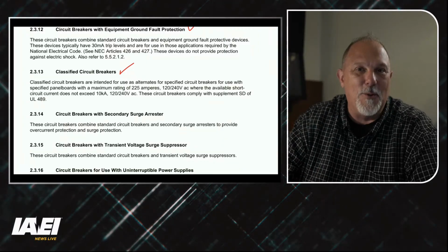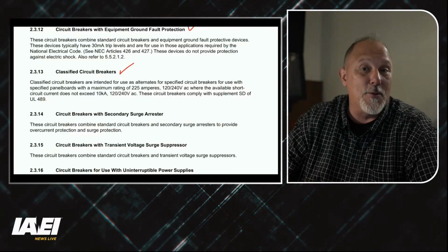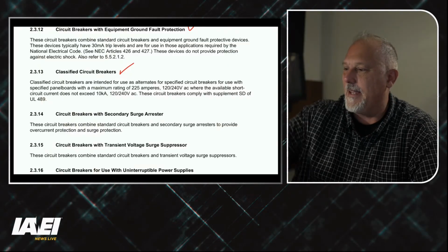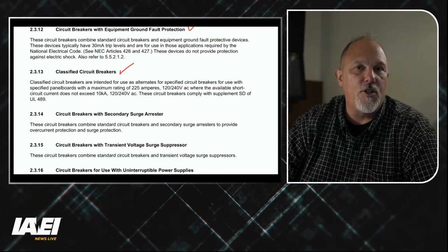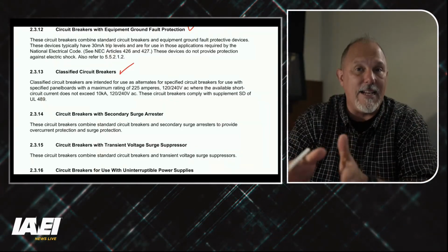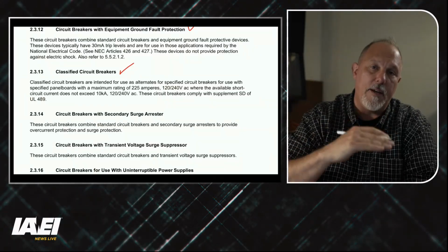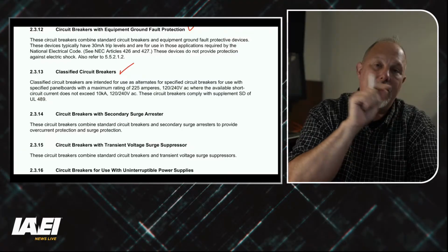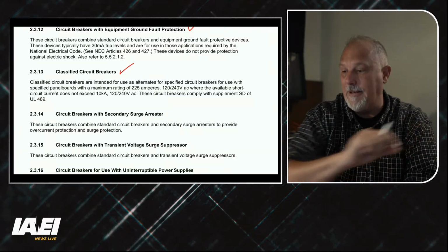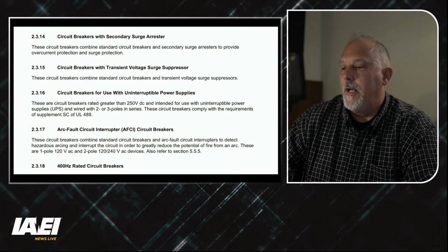I live a short while away. And she was going to do that, but the manager of the store didn't like it, so lost the sale, I guess. But you have to make sure that the breaker matches the panel board, unless it's a classified breaker. And if it's a classified breaker, they'll tell you all of the panel boards that breaker was listed and tested in. All right, so that's the classified breaker program.